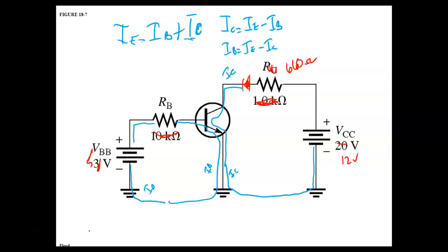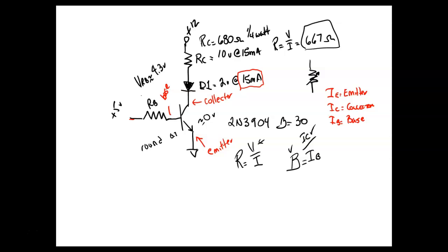Okay. So what we're saying right here is that this is a new formula. It's the gain. Gain is always out over in. It's always out over in. So in, we're putting IB, that's our input current. IC is where our load's connected. So this is beta.